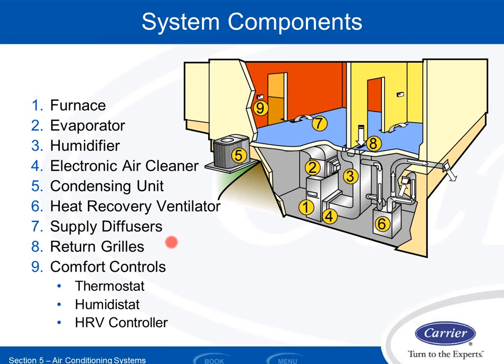We have to have some type of air distribution system. There are systems that are not ducted, right? So radiant floors, for example, radiators, fan coils, variable refrigerant flow, duct-free splits. But much of what we do residentially and commercially is ducted systems. That's the most common scenario in the United States. So we need some sort of ducting system. Typically that consists of a few main components.